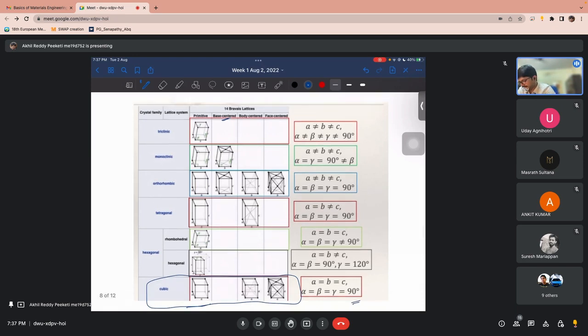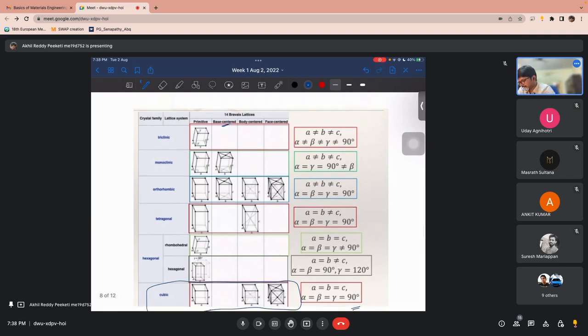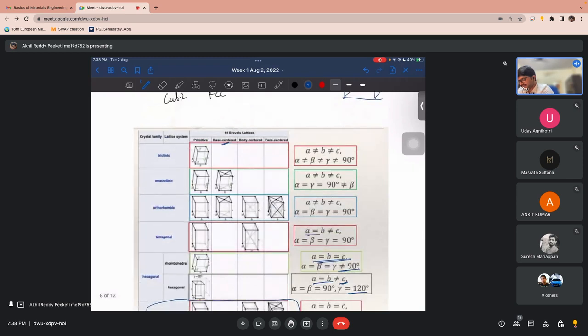But in reality, other cases are also possible. The unit cell dimensions do not have to be the same. If all the dimensions are equal, it is cubic, and if the third dimension is different from the other 2 and the angle is 120, it will be hexagonal, similar to the HCP system we are seeing. In rhombohedral, the angles are not 90 but the dimensions are equal. And in tetragonal, the first 2 dimensions are equal and not equal to the third, but the angles are all 90.